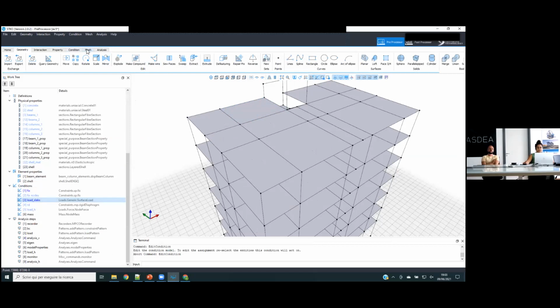Okay. So if you want to use the rigid diaphragm approach, you don't have to mesh it. These surfaces are only used to transfer the load from the surface to the boundary edges, and you can also do without them. You can just apply the edge loads if you want to calculate them by hand. Instead, if you want to use the shell approach, you take those surfaces, you discretize them, you assign an element, a shell section, and then you apply a face force on that. And finally, you discretize it based on the kind of analysis you have to do.